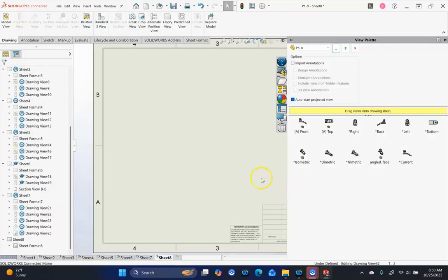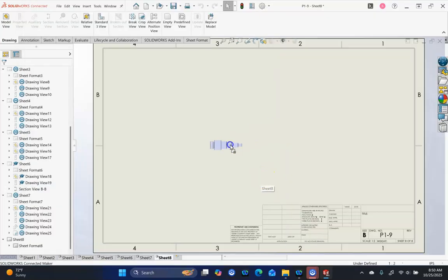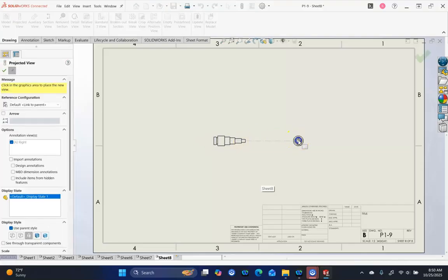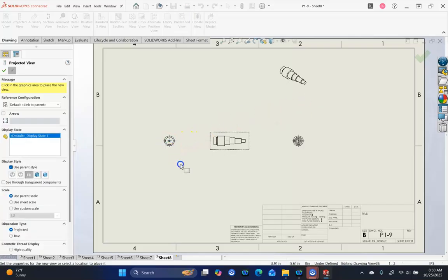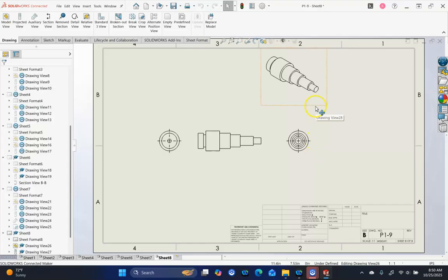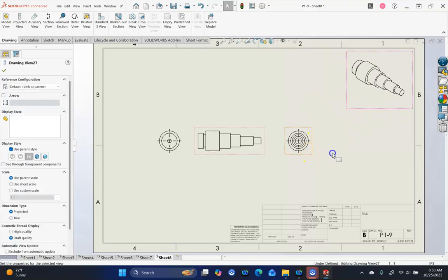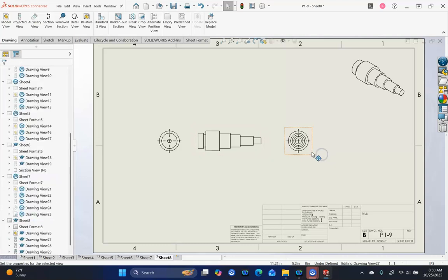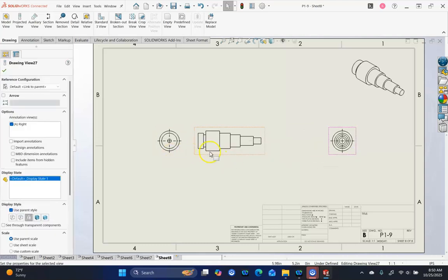All right, we have the revolved, so we're going to probably want to view projected that way, the isometric, and since there's also geometry that way, we'd want to be able to utilize those shapes. Size-wise, let's see what 1:1 looks like. Okay, that's not too bad. So we can open that spacing, and I'm just looking for the view to highlight, left-clicking and dragging.